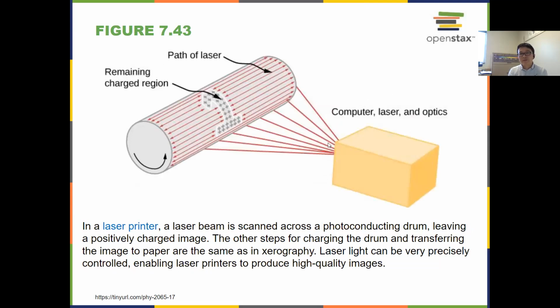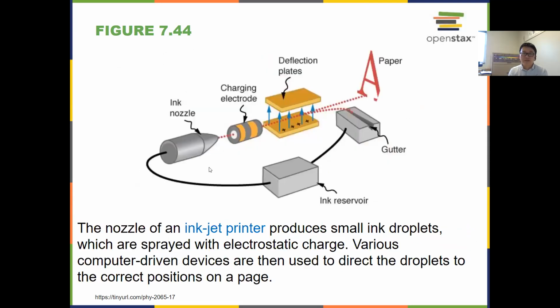The inks are charged, and there's an electric field in there, so you can bring the printing to any specific point you want. Another illustration of that: electric field, charged electrodes, and the inks being here, projected to the specific location on the paper for printing.